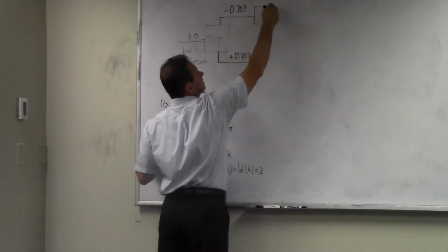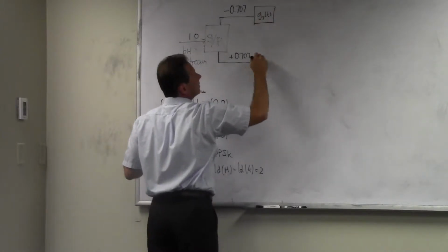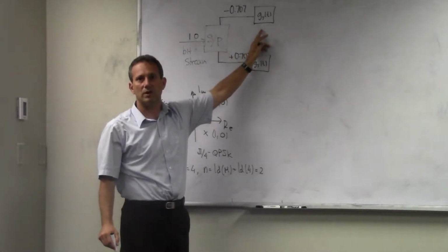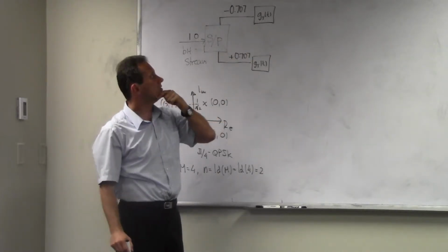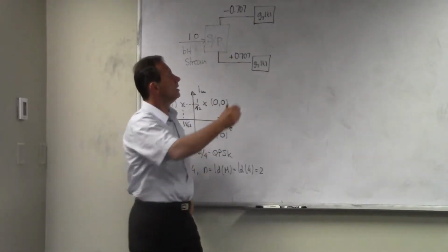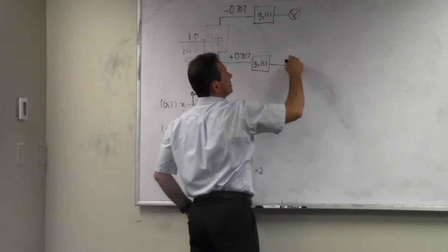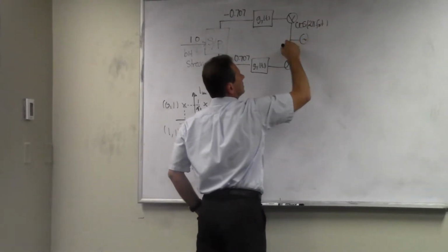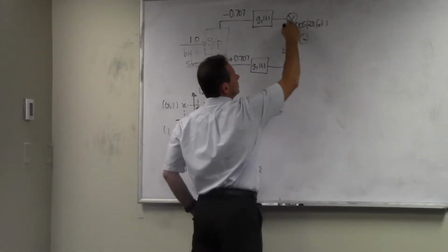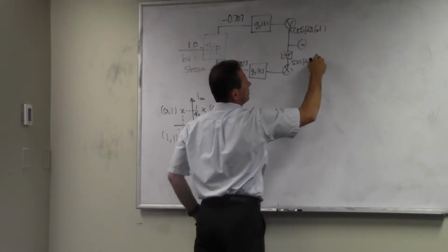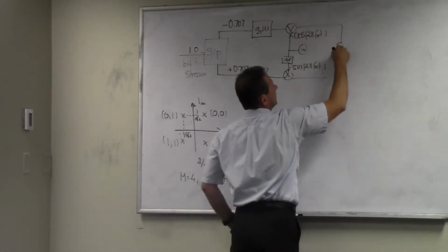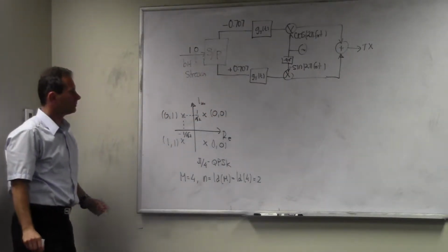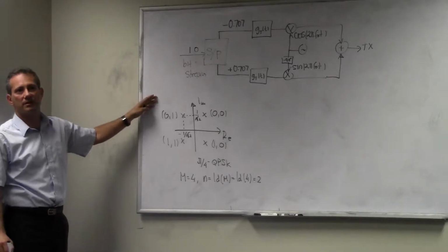And then this would excite some analog filter, which you can actually either put as a real analog filter, or more likely, this is a D to A converter that's just going to be spitting out the samples of this g(t) scaled appropriately with this gain. And then you go into essentially your modulation stage, where you're going to have an oscillator here. This is your cosine 2 pi f0 t, and this is shifted minus 90 degrees to give you here sine of 2 pi f0 t, probably minus sine, and then you're going to take these two, add them together, and this becomes the transmitted signal, right? So that's your waveform that gets transmitted. Now this is assuming that you're encoding 2 bits at a time, right?